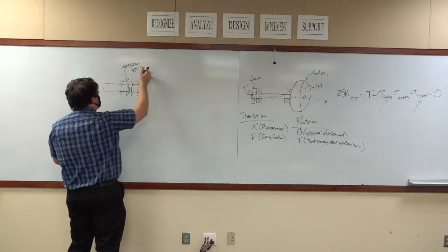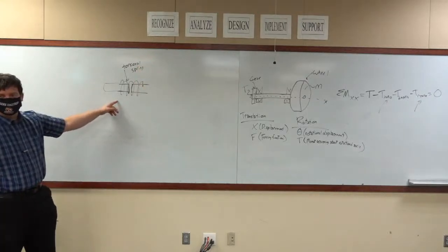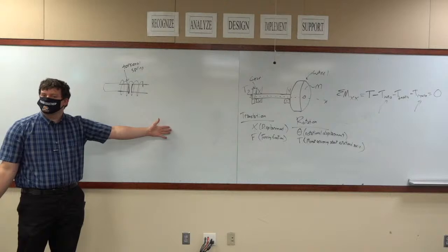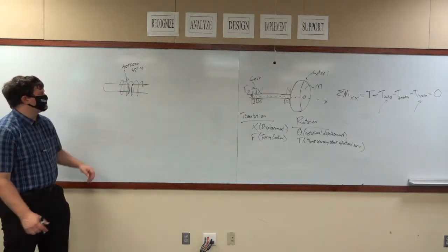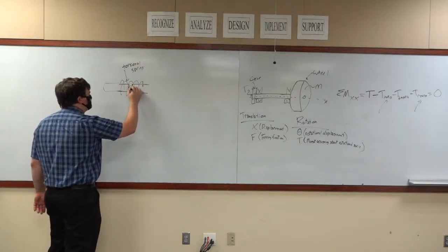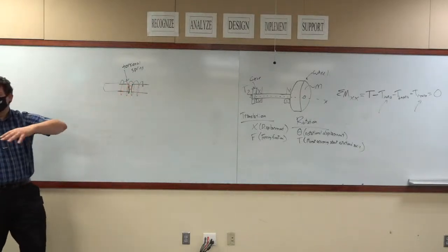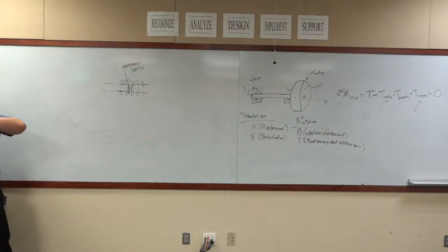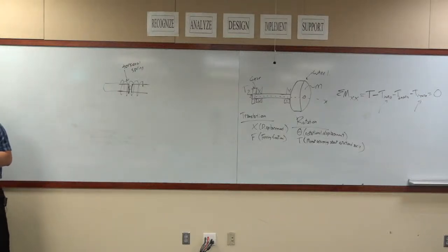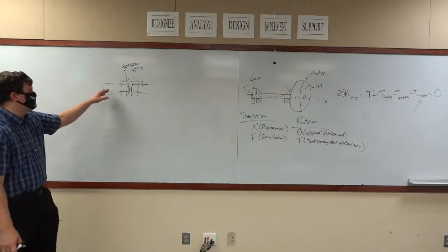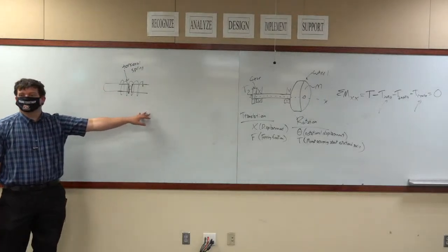And what this does is this transfers torque from one axle to the other. Maybe they're both riding on some other, but it is actually the torsional spring that transfers torque from one axle to the other. Without that torsional spring, this axle spins independently of this one.